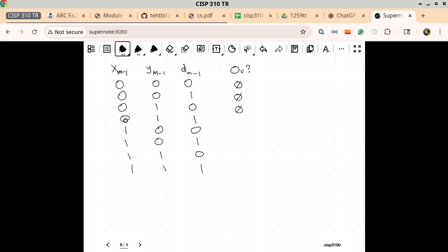We look at this one, which is a non-negative quantity minus a negative quantity ending up as a negative quantity. Does that make sense to you? It does not. It should not. Okay. So we have an overflow situation here. I don't even care about the rest of the bits. Just looking at the sign bits, I already know this doesn't make sense. There's overflow. Are we still doing okay so far?